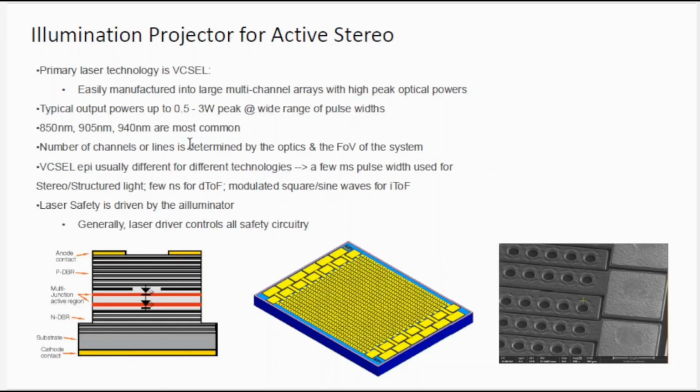Okay, the other thing, I'm not going to spend too much time on this slide, but generally in consumer electronics, what you'll find is VCSELs are traditionally the projectors of choice. In terms of the collimation and in terms of the control that you can get, they work far better than LEDs do. And then when you go into time of flight, you need to be modulating. So I think VCSELs end up working out the best.